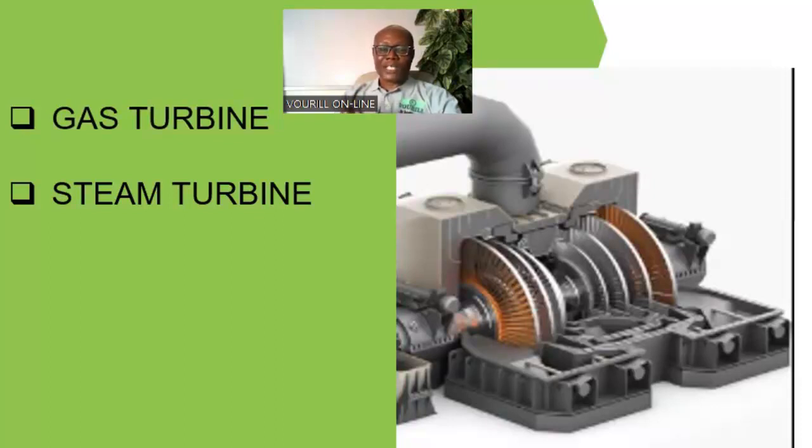Which means that the chemical energy in the fuel is first converted into heat energy, and then the heat energy is converted into the kinetic energy in that fast moving steam, because as the water in the boiler absorbs the heat, it will evaporate to form steam. And as you heat further, that steam will gain more energy, and then move downstream.